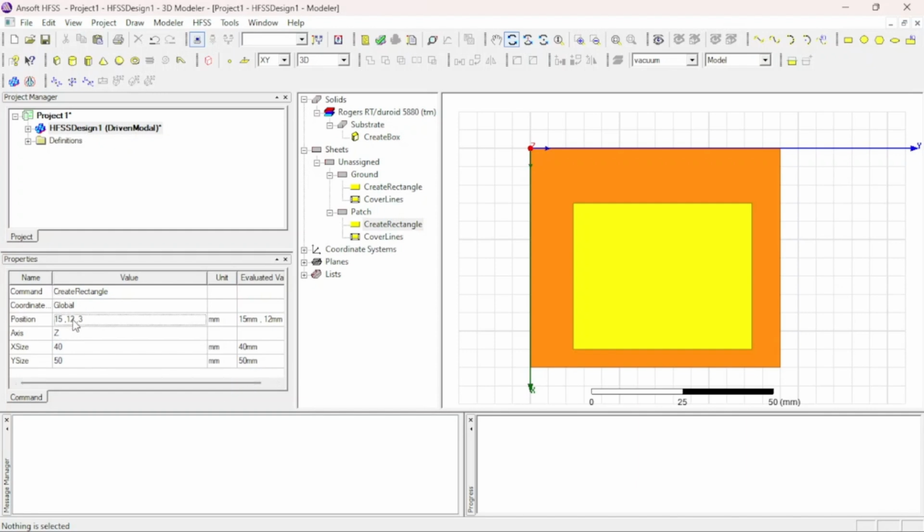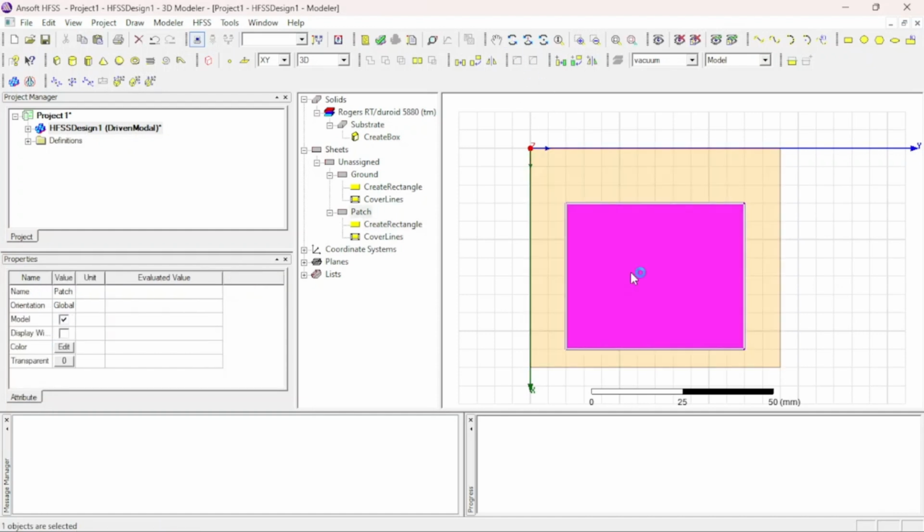So it will work according to your way, guys, how you want it. Let me give it 10. Okay, so it has moved further, but you may wonder how I am deciding whether it is at the center or not. Am I just deciding by looking at it? No. For that, just deselect the rotate option and click on the patch. Look at the squares on the left and right side of it. On the left side, you can see two cells, and on the right side also you can see two cells. That means that the patch is at the center, at least along the y-axis.